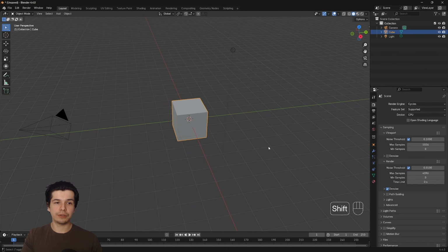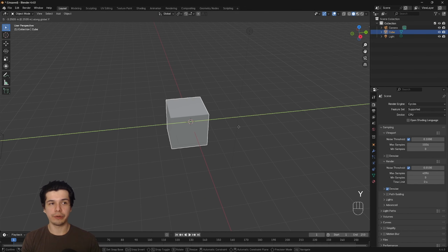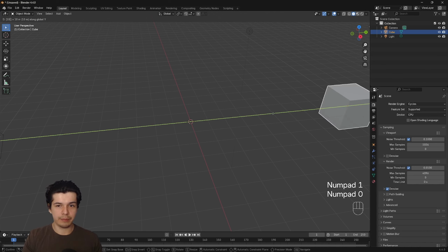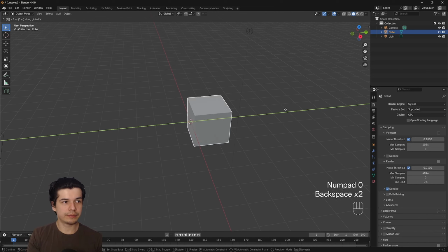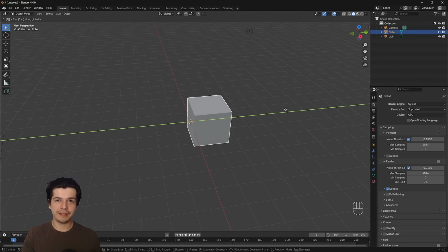Another thing you need to know is when you press G and, for instance, Y, and write any number, you can see in the left corner moving numbers. You can write these numbers, which means you are locking it to the number, so if you move the mouse, it doesn't work anymore. So I can press 100, I can press 5, 1. If I want to apply this movement, I left click and it's there.